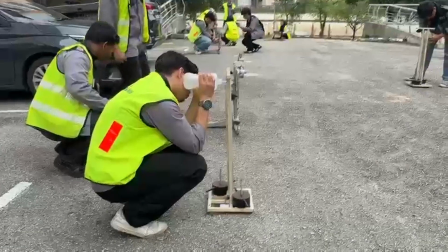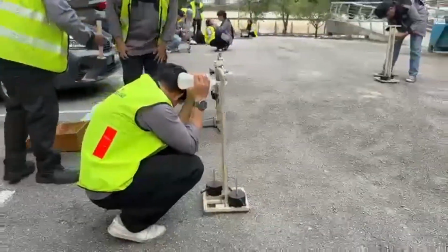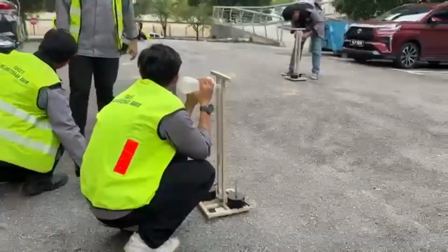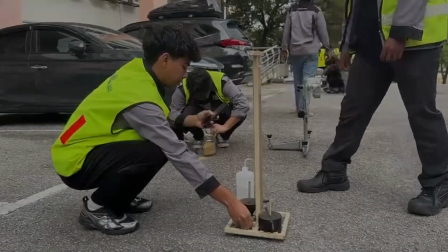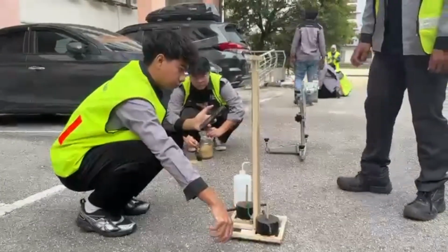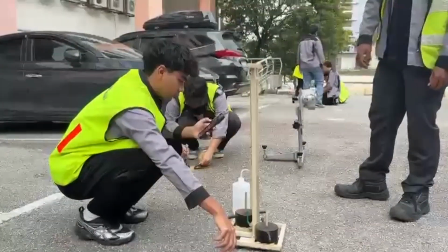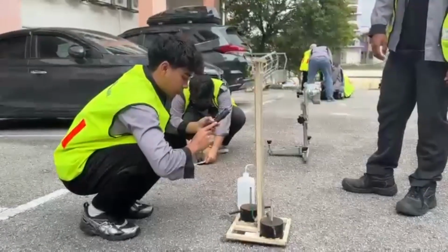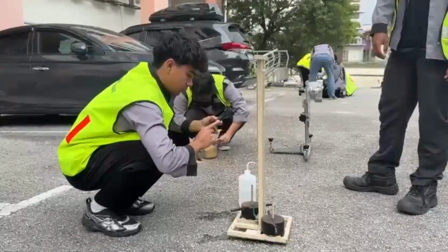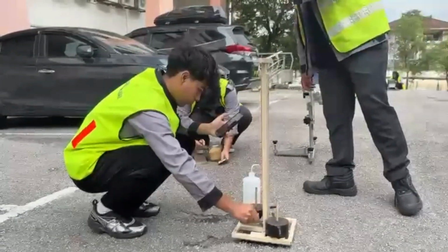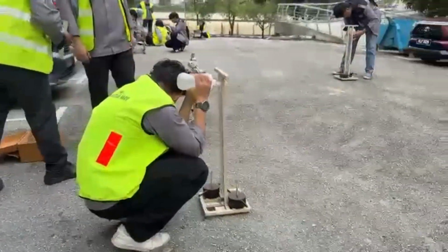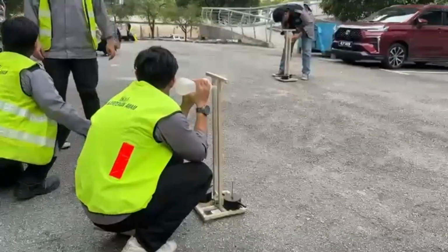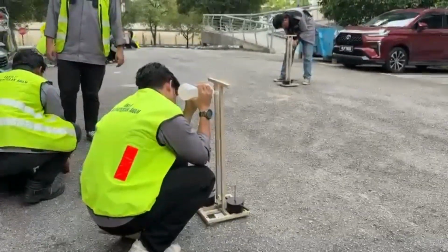The final test is the outflow meter test, which measures how quickly water can escape through the pavement texture. We place the outflow meter cylinder onto the surface and ensure a watertight seal at the base. We then fill the meter with a standard volume of 400 milliliters of water. The valve is opened, and we start a stopwatch immediately. We record the time it takes for the water level to drop between two marked points in the cylinder. A faster time, as seen at location A, indicates a rougher surface with better drainage properties.